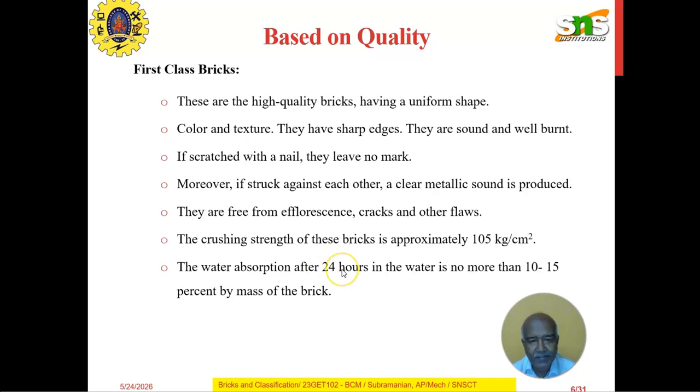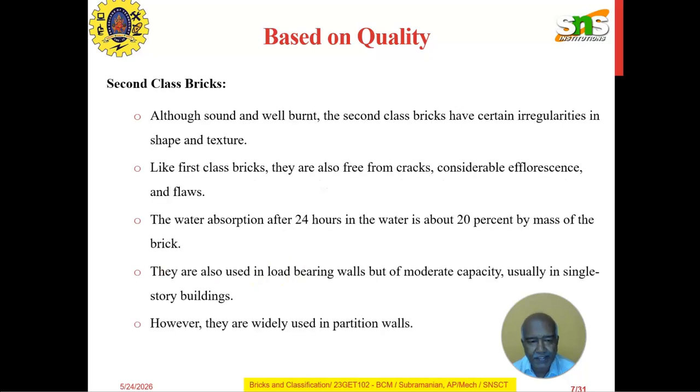The crushing strength of these bricks is approximately 105 kg per square centimeter, which cannot be achieved manually. The water absorption after 24 hours in water is no more than 10 to 15% of the mass of the bricks. Next we see the second class bricks.